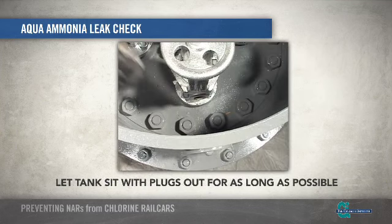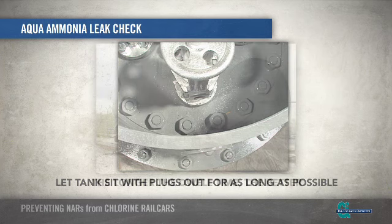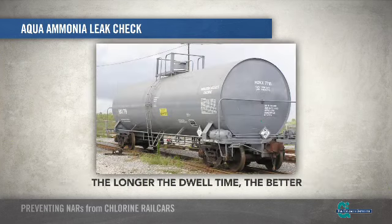When checking for valve leaks, let the tank car sit with the plugs out for as long as possible before doing a final aqua ammonia leak check. The dwell time will allow smaller leaks to develop and become detectable. The longer the dwell time, the better.